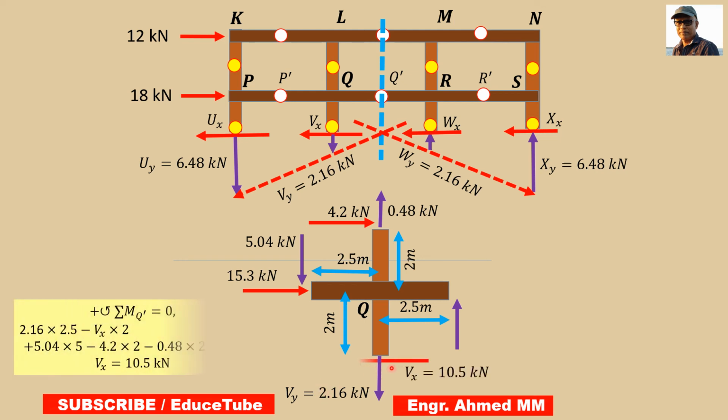So summing the moment equal to 0 about this point, this point means Q prime. So we got 2.16 multiplied by 2.5, then 5.04 multiplied by this 5, then minus 4.2, this one, multiplied by these 2.48 multiplied by also 2.5.